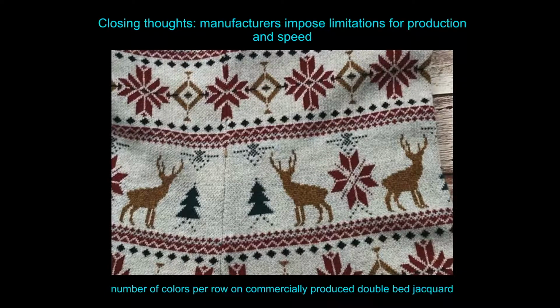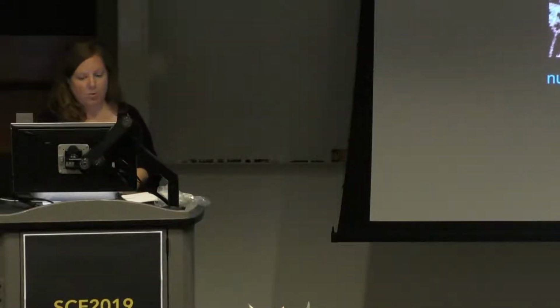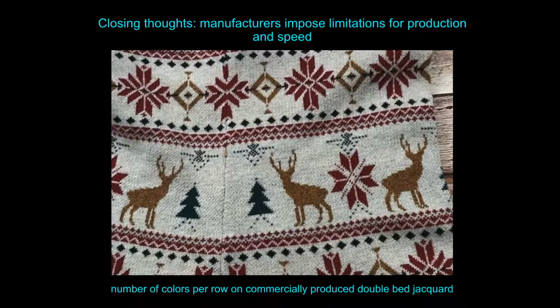So as closing thoughts, I just wanted to put it out there that manufacturers impose limitations on production and speed. This is an unusual example because usually the number of colors per row on commercially produced double-bed jacquard, which is the type of structure that I'm handing around, is 3, because most people have 3-system machines, which means you can do 3 operations per pass, and so most manufacturers limit themselves to 3 colors per row. But this actually has 4 colors per row, so you can see that dark green, white, gold, and the red are all in the same row.